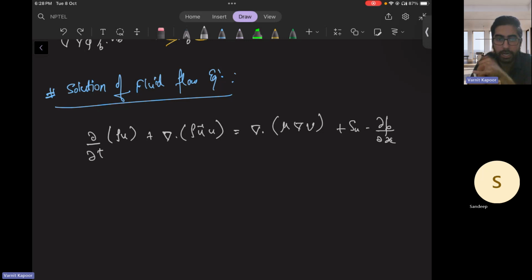So if we consider a 2D scenario, the x and y direction, both sides the flow is happening. Instead of one equation, we'll be having two momentum equations, x momentum and y momentum equation, where phi is replaced with u and v. Also, we have a continuity equation in addition to these two equations in fluid flow problems. Okay. So if we compare, our equation will be like this compared to the general transport equation. All right.